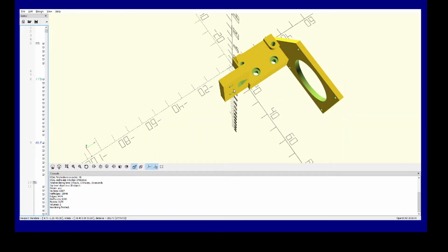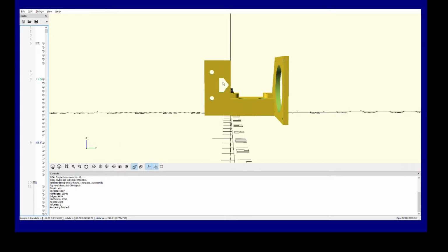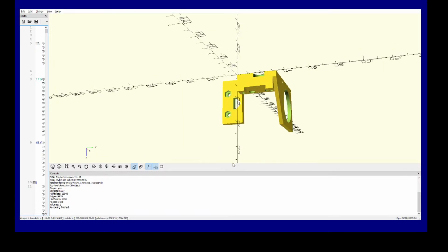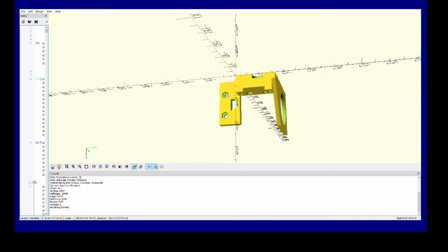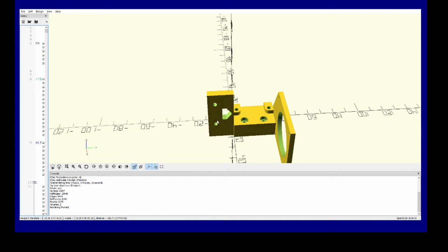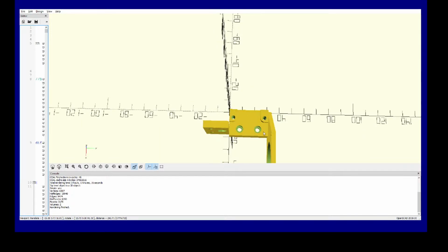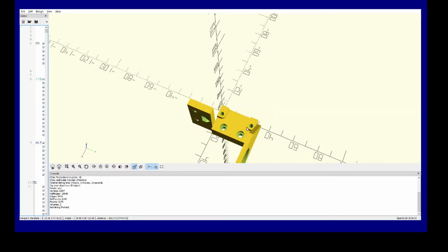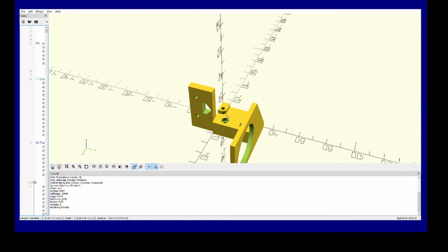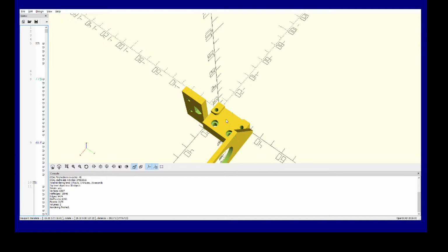This I need to clean up. That's where the BL Touch will go. But I'm trying to figure out wire management for this right now. And I put countersinks up here so you can just screw it into a 3mm bolt. You just bolt right through it. And then it also can countersink into this by threading it when you're bolting it. The same goes true for everything else here. Everything is designed to hold the part in a certain way. This is designed for the dual color extruder or hot end. It just slides into here after it's been bolted on.